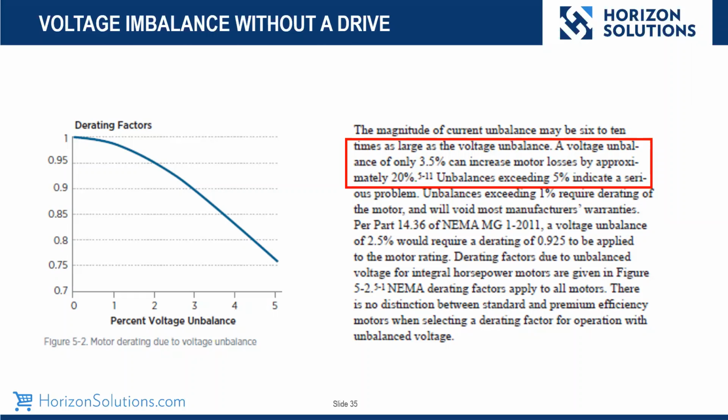You say, well, I'll put a drive in front of it. That'll take care of everything. It won't hurt the motor any. I'll be all set. Well, it also damages motors. So it's very, very critical that you address the issues with your voltage unbalance in your plant, rebalance your single phase loads, and that will cause a lot of serious problems mechanically and electrically with your motor driven processes. Next slide.